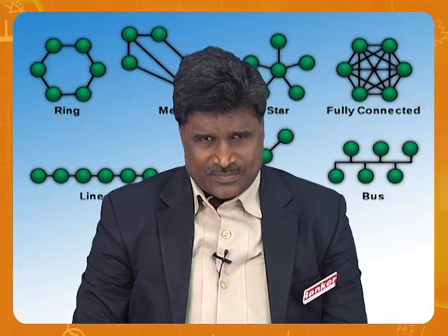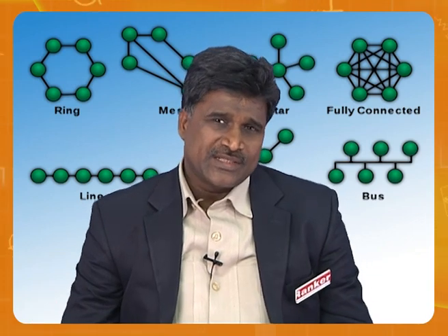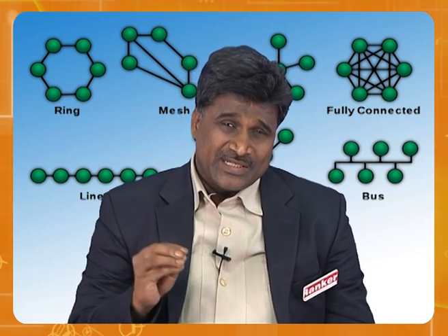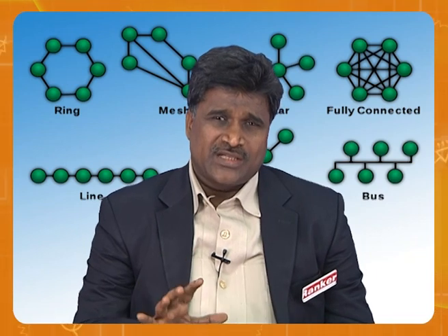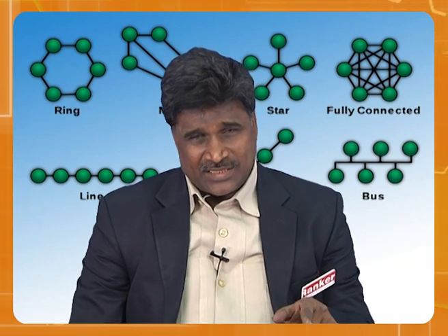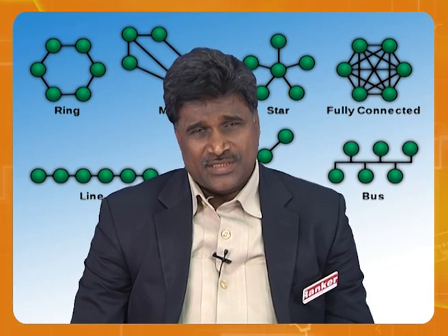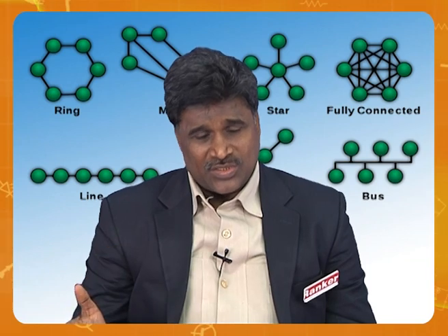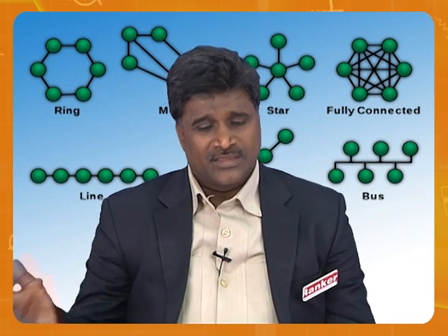So like this, we can have a cut set matrix. For the cut set matrix, you follow the arrows. With these 3 matrices done, 90% of the chapter is over. And tie set and cut set are more important than the incident matrix. Please remember, the incident matrix is to understand whether the circuit is complete or not, connected or not. But tie set is to calculate the currents and voltages. And cut set is also to calculate voltage and then currents.